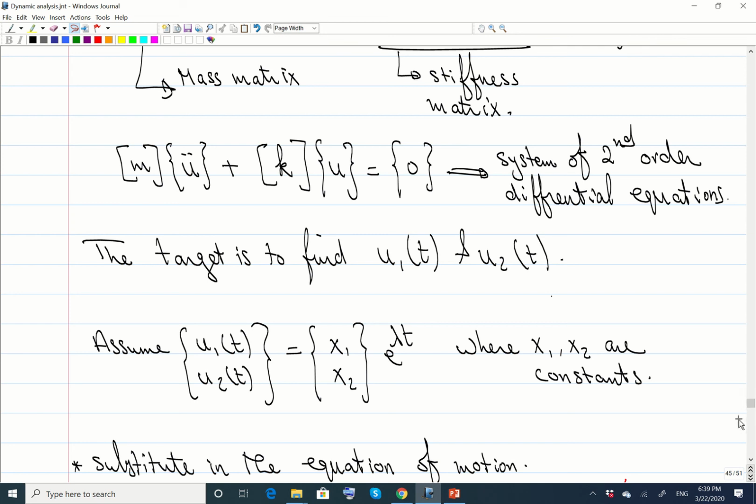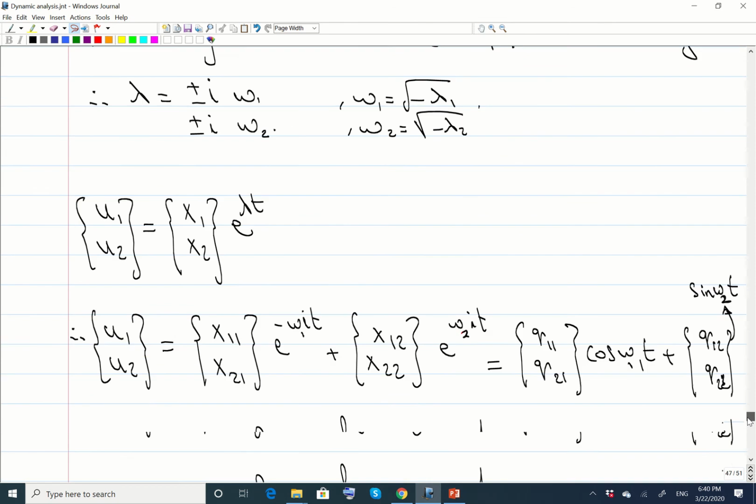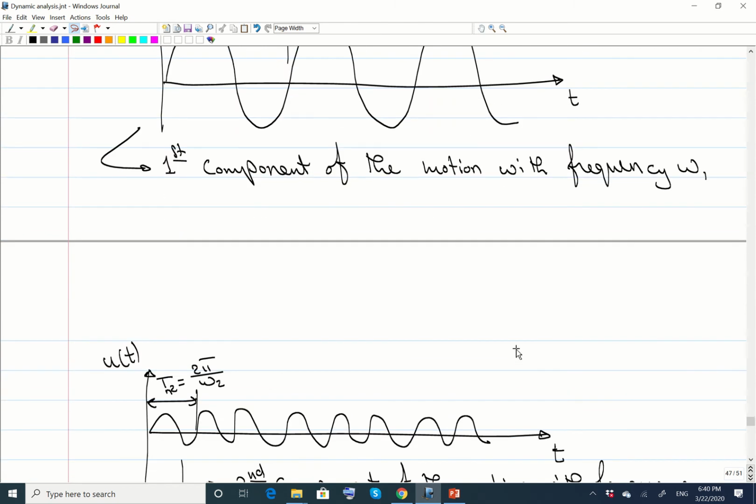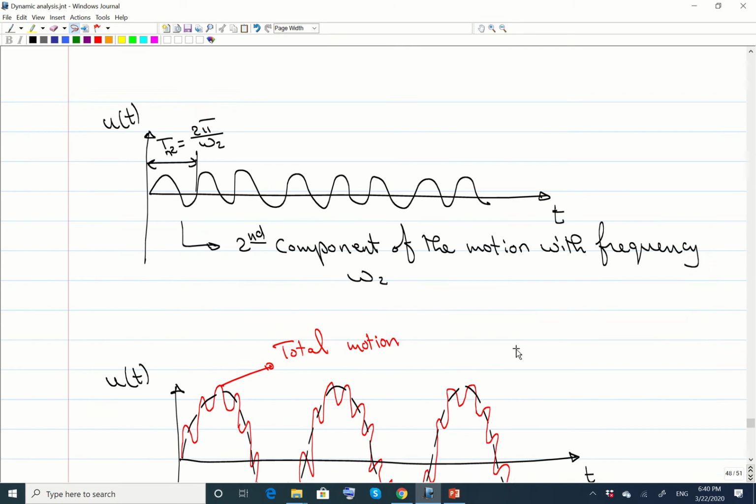So actually, when we do this modal analysis, we can extract or find only the lowest frequency, and then later on, if we want to find the forces that come on this structure, we can base this only on the lowest mode, the lowest frequency.